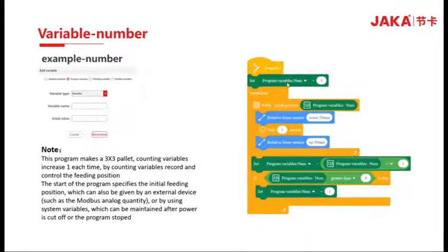We set a variable called num, and we input the value 3 inside. Then we have a repeat loop for the whole operation and a function of a palette. Inside this palette, we have two linear motions, down and up, like to pick up a part. The initial position will be the position inside the variable. Here in the example it will be 3.